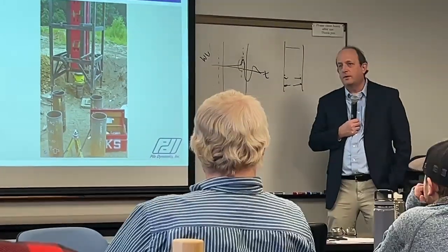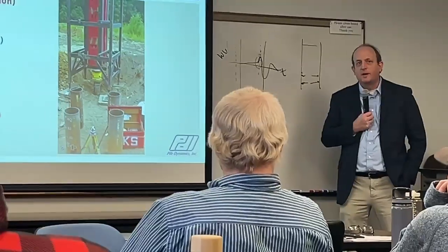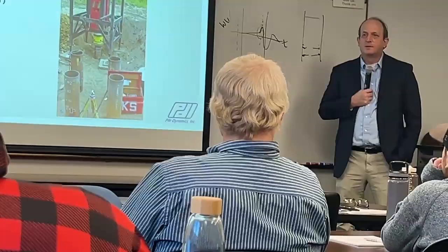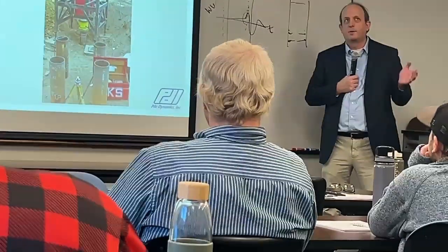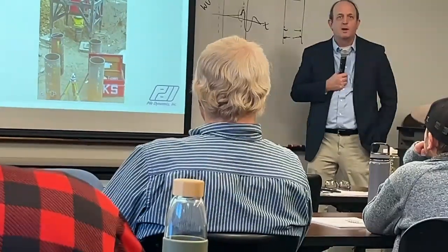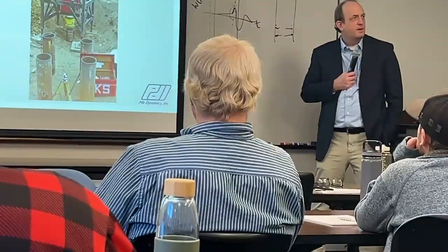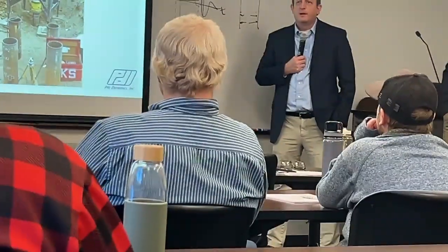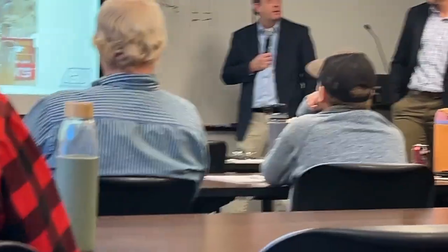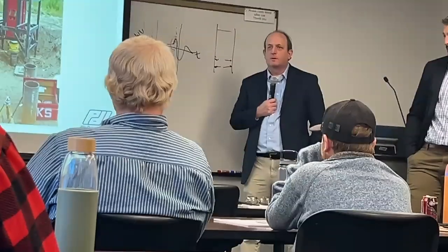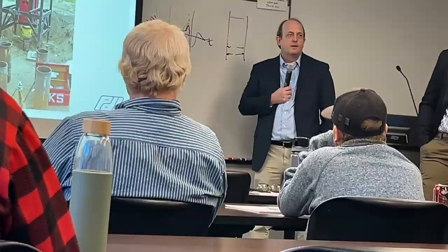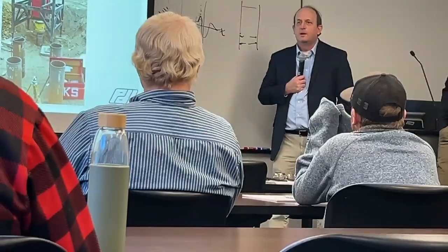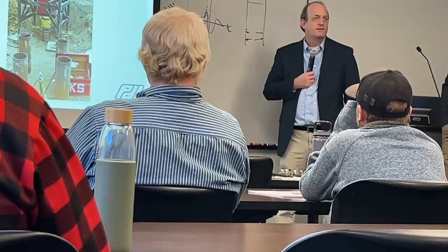So that's something else that sometimes pops up in open piles, especially in scenarios where the open pile and the static load tests agreed. So that's what came out of Kentucky Lakes, I think. And part of those were non-restrictor plate open-end pipes, and some of them were restrictor plate open-end pipes. And having done probably a half dozen of the restrictor plate type jobs, I don't recommend them because they never behave quite like you imagine they will.